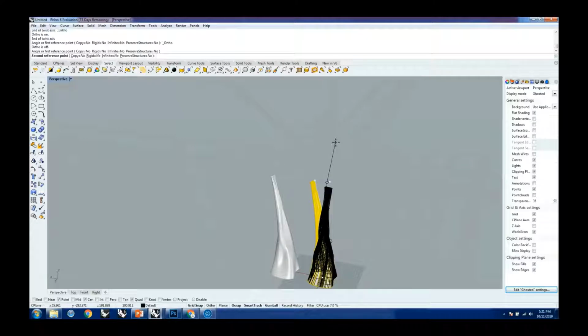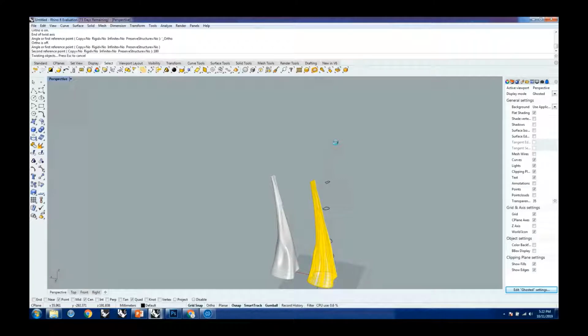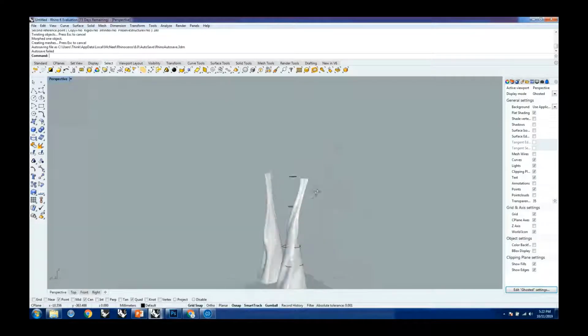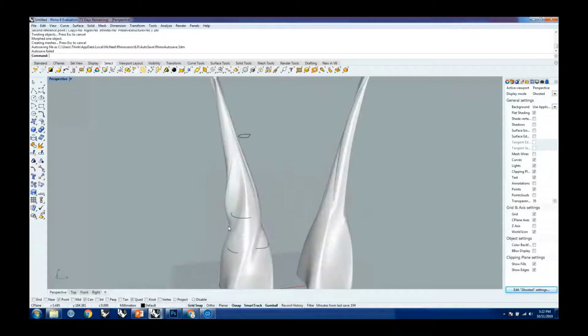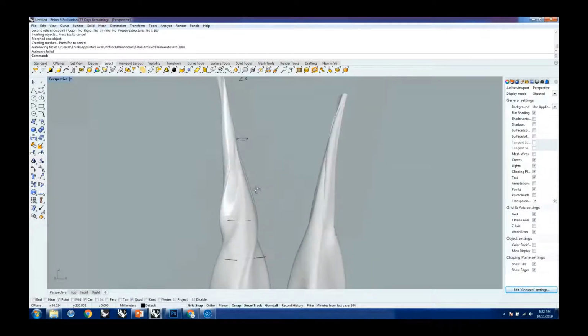Let's say I'm going to twist it by 180 degrees. Okay, let's not pick some reference point. I'm just going to type the angle. So you have the option of typing the angle, the rotation angle, or you can pick a point randomly, just like in bend. Okay, so I hit OK. It takes some time, of course, because bending and twisting takes time. Okay, and there we go. That's the geometry. That's how it looks.